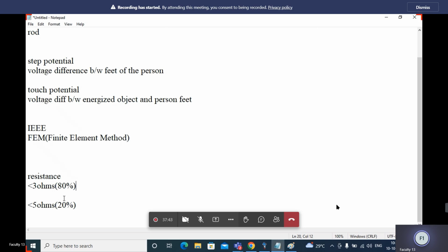In some places, if the fault current is very low, after filling coal, soil and salt, finally they will assign the water. In other places, they include the water in between itself. Why? Because after that we are not going to open that earthing part, right? Only if any fault or problem occurs will they open it and see the fault. So that is the reason they provide water and then coal, soil, salt to reduce the resistivity. Okay. So now I am moving to the ETAP software section.